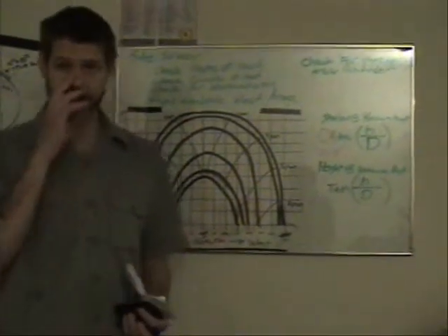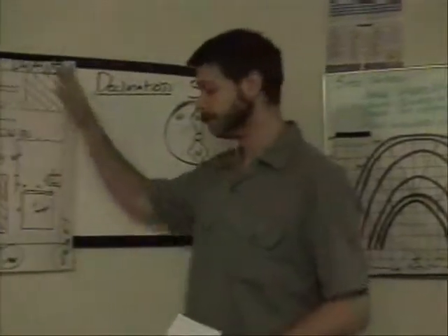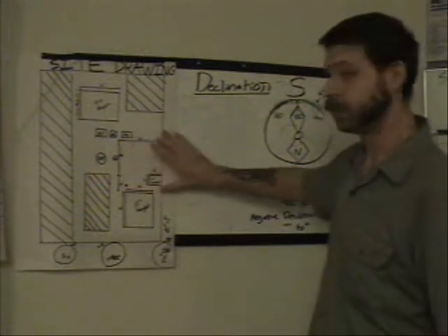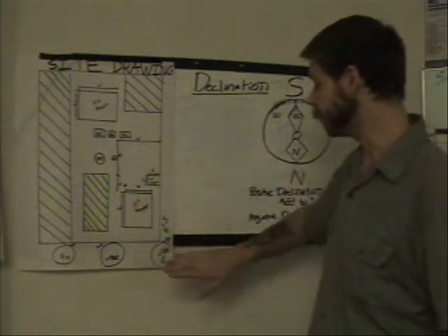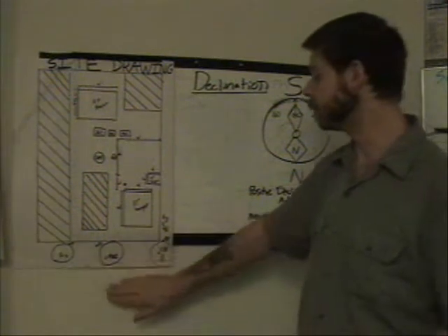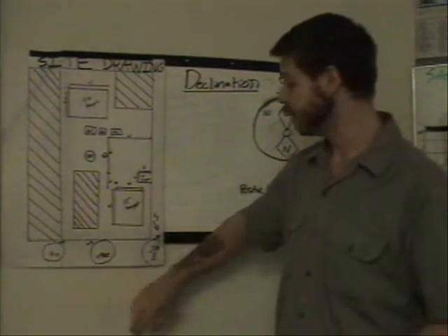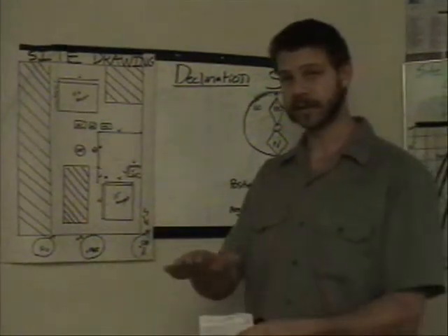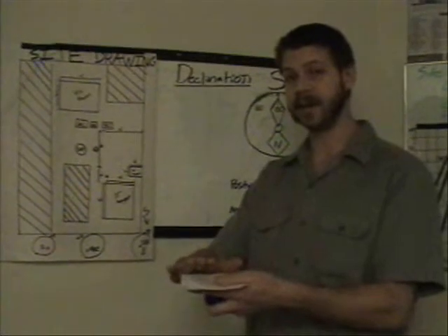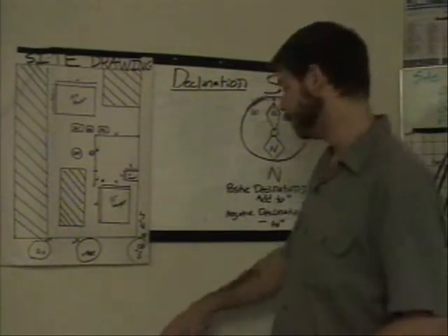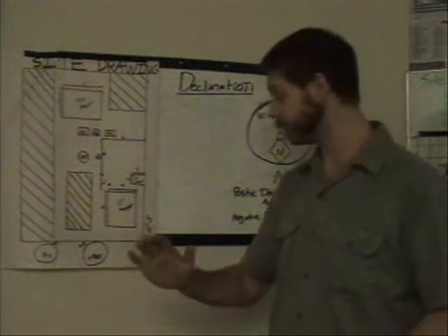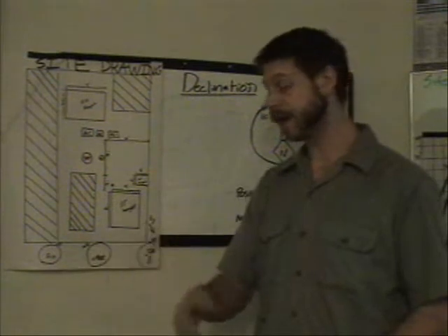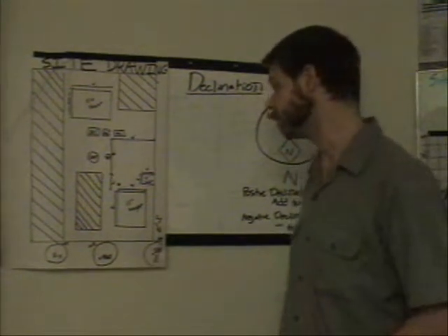Now, if you take a look at the site survey, this is our site drawing. This is the area we wanted to put our solar array in, and there were three trees. One at 180 degrees, one at 200 degrees, one at 215 degrees. They're each about 5 degrees wide, and the angles that we measured with a protractor by taking a level plane and angling up from the ground. The 180 degree tree was at 26 degrees, the 200 degree tree 31 degrees, and the 215 degree azimuth angle tree was 15 degrees above level.